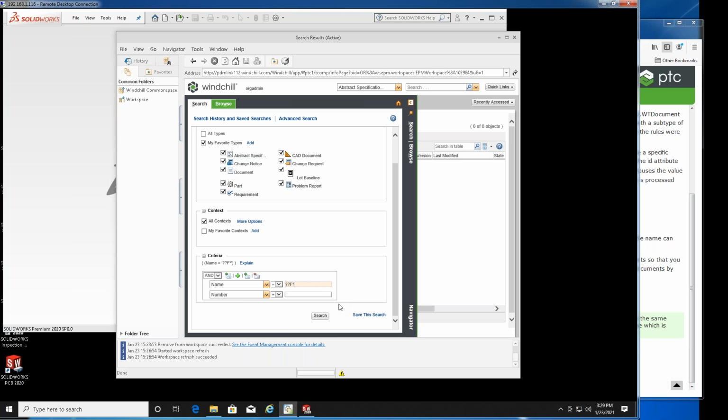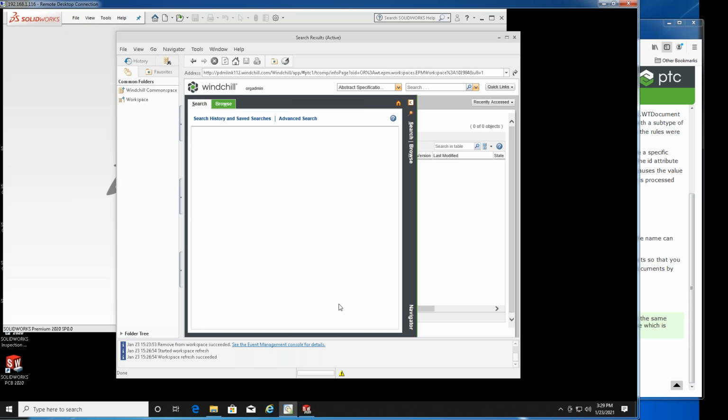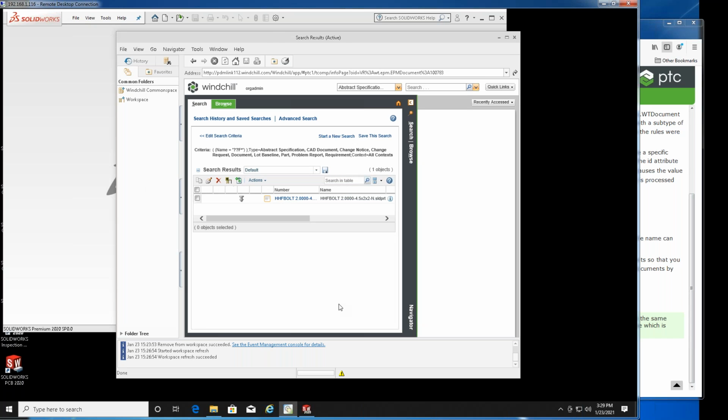So you could set up the search as so. 2 placeholders, a question mark, the letter F that I'm interested in has to be in the 3rd place, and whatever follows, that's fine. I'll navigate from there. Hit the enter key and it goes around and finds that particular bolt for me. So this is sort of the approach to using these syntax. They're very, very handy. And those could be used in description and whatever you like.